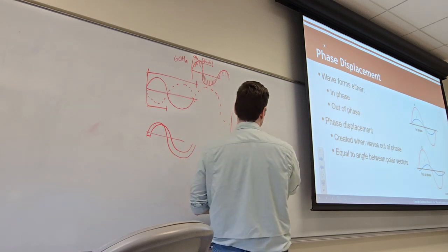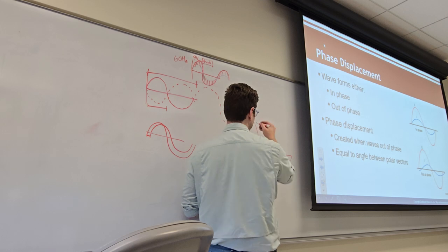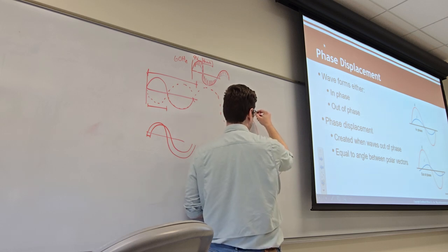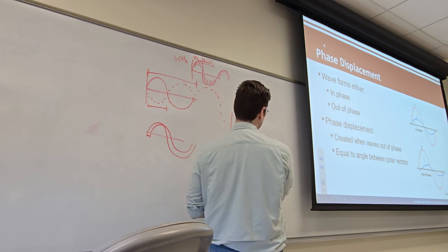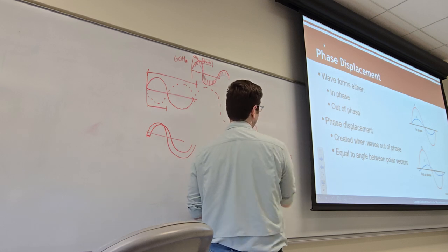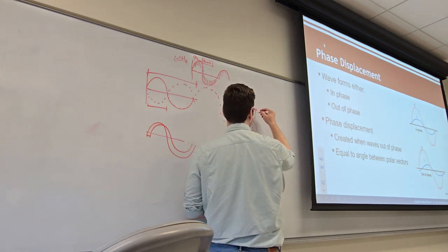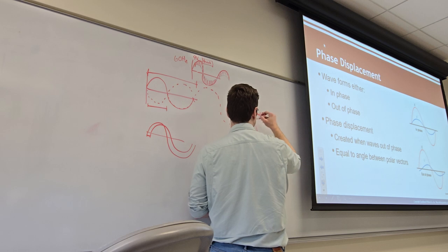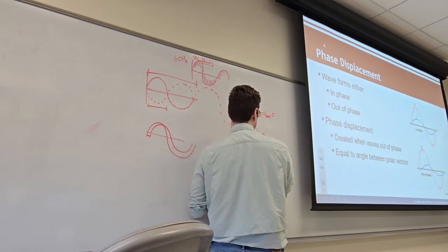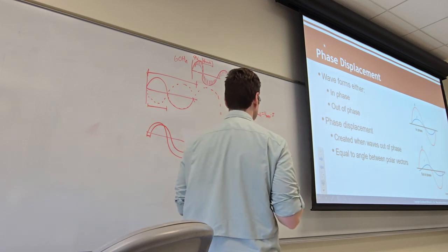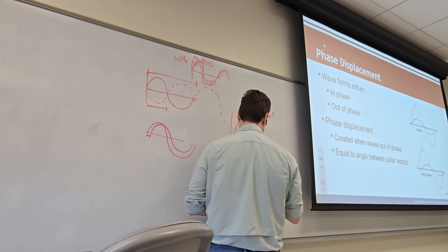This offset lowers our peak available current, okay? So see how our maximum possible power is no longer what it could be because the maximum current no longer happens with our maximum voltage. So our P max equals V max times I, right? It's not at its maximum point, so it'll be lower. Okay, this is what we call power factor.